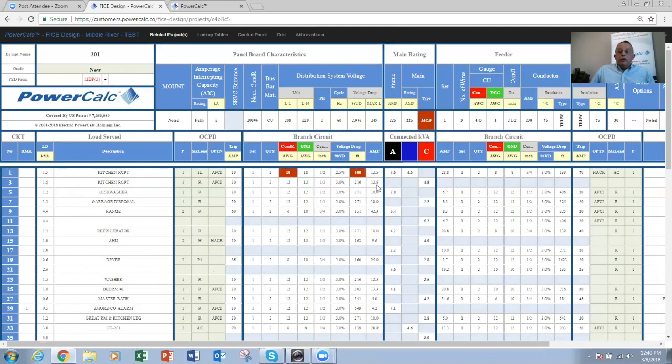Feet. Okay. Now, let's say that the furthest load is further than the 216. If it's further than 216, that means your voltage drop is going to be higher than the 3%. But in order for you to keep it at that level of a 3%, the only other choice you have is to upsize the conductor size. So you need to go from a number 12, or maybe from a number 12 to a number 10 or a number 8, depending on the distance.